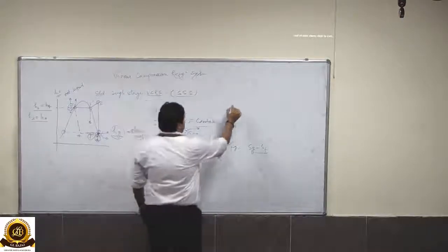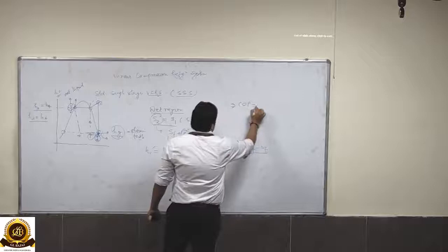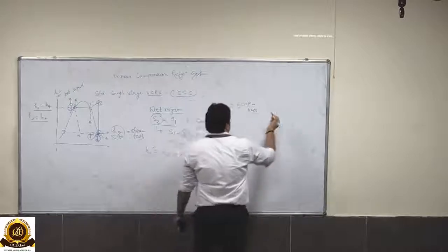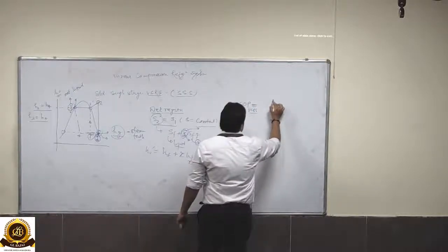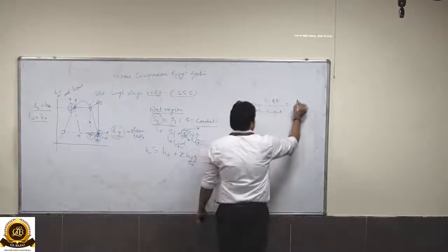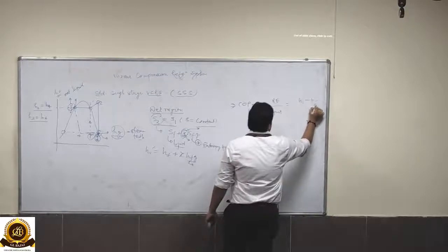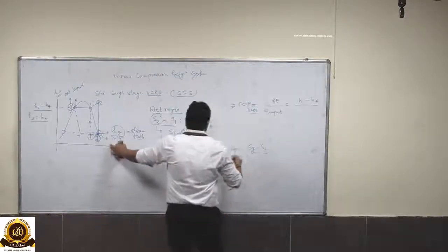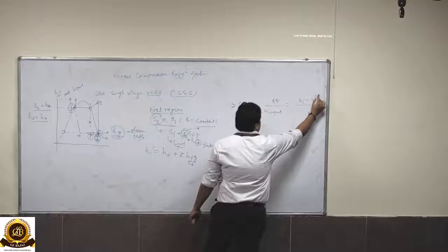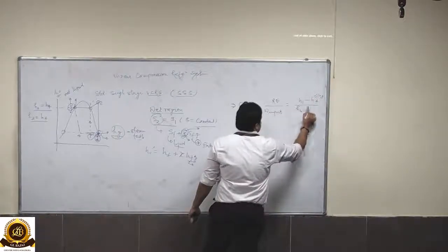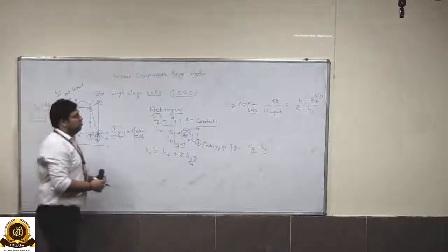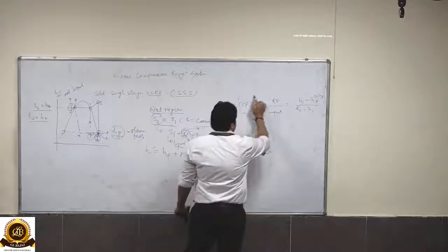So from the formula we can calculate the COP of the VCRS cycle, or a standard single stage cycle, as refrigeration effect divided by work input to the compressor, that is H1 minus H4 over H2 minus H1. We know the value H1, and we know H4 because we know H3. So from this lecture we have concluded that the COP of the VCRS cycle can be calculated like this.